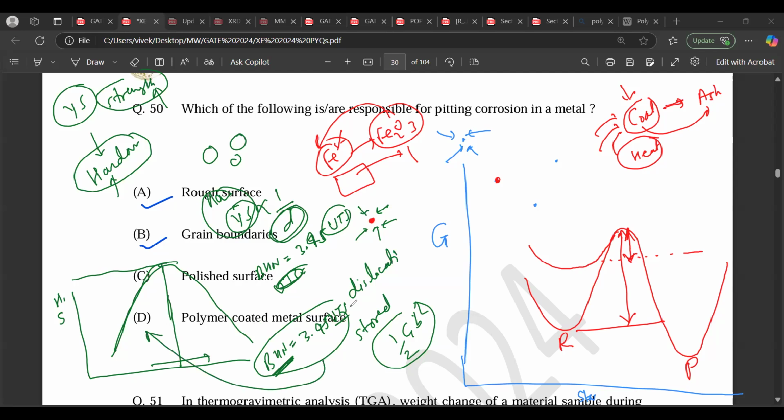Okay, the fundamentals. Hardness and UTS behave similarly to strengthening with precipitation. Why is that happening? When you're measuring the strength, the more obstruction to the dislocation motion, the more the strength. If the dislocation can move easily on the slip plane, the lower its strength.